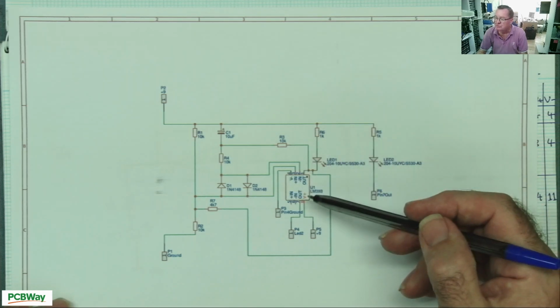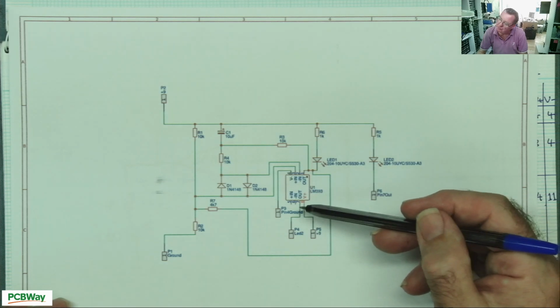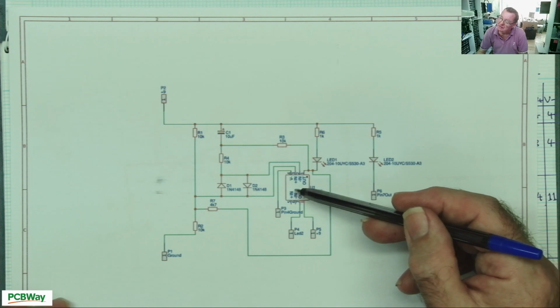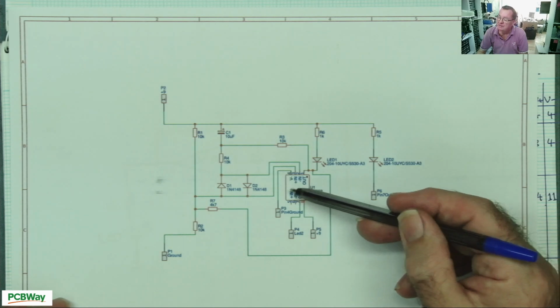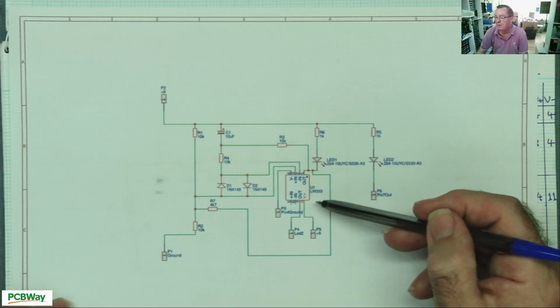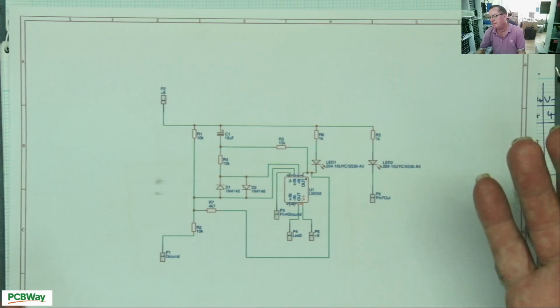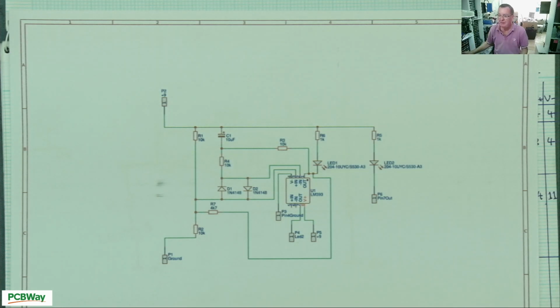This is a bit of a strange schematic, because if you look at it, pins 5 and 6, which are the inverting and non-inverting inputs to the second comparator in here, are not connected to anywhere. They don't go anywhere. But the output, LED 2, goes to here. So I'm thinking that can't be right. Yeah, so let's have a little bit of a look at this.